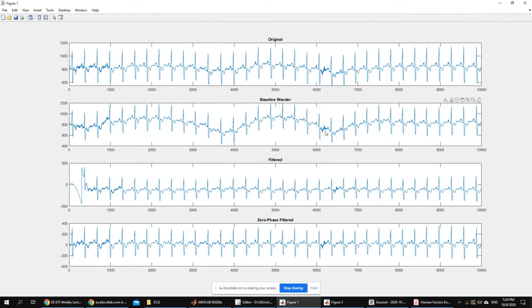If you try to subtract these two together, you will have a problem because of the mismatch. The outcome is a little bit shifted from the income. The input and the output of the filters are not synchronized. The points are not matching each other. So you have to take care of that by shifting the array by the amount of the group delay.